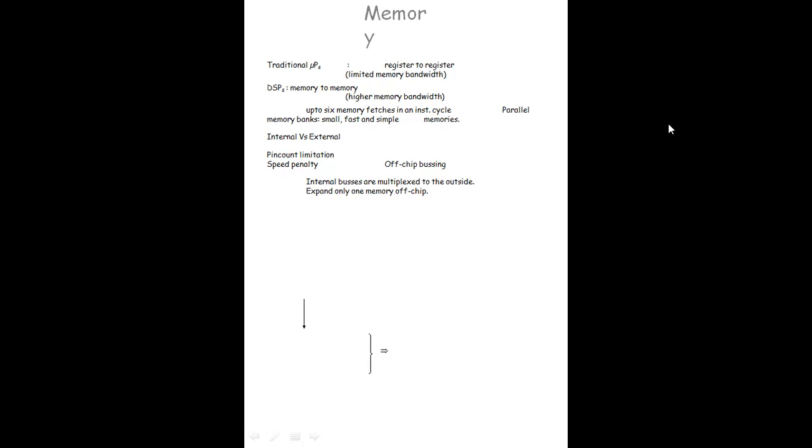So this is the major thing to be seen in the case of DSP processors. They are special purpose digital signal processors, specifically required for DSP processing applications. The normal microprocessor does not have these special features like pipelining, multi-port memory, multiple access memory, modified bus structure, and multiplier and multiplier accumulator.